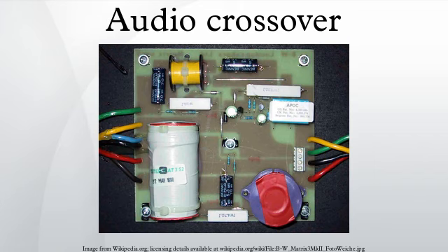Parallel crossovers are by far the most common. Electrically the filters are in parallel and thus the various filter sections do not interact. This makes two-way crossovers easier to design because the sections can be considered separately, and because component tolerance variations will be isolated. Parallel crossovers also have the advantage of allowing the speaker drivers to be wired separately.